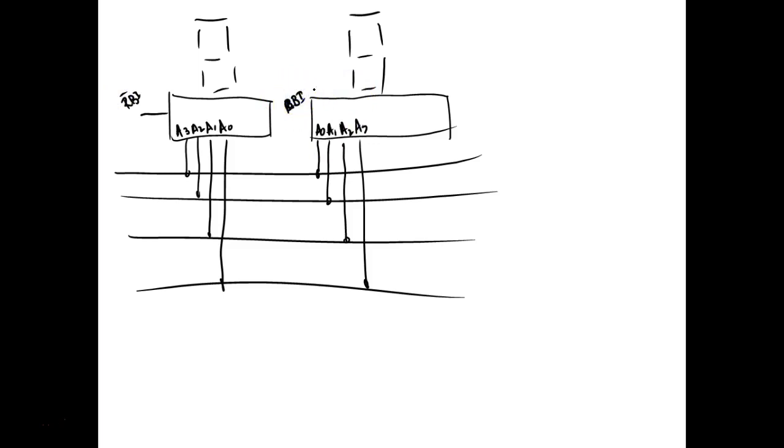I think it's low active. So what would happen is it would come over here, and if it put a 0 here, it would put a 1 right there. These would never be energized at the same time. And whatever is on the data bus, this guy would decode it, and it would come up here, and let's say this guy displays a 3.